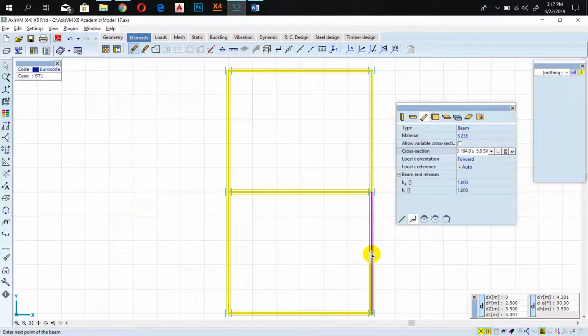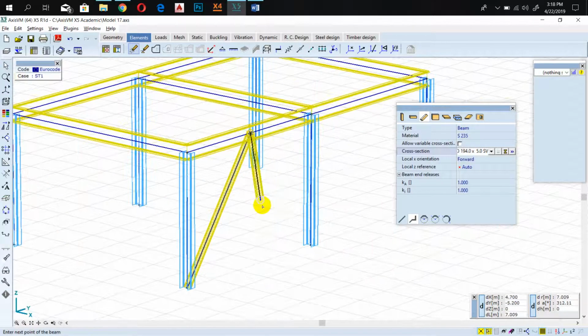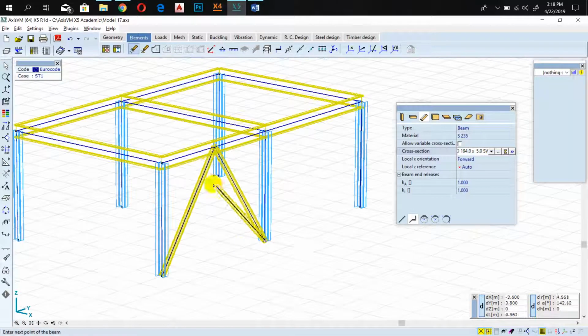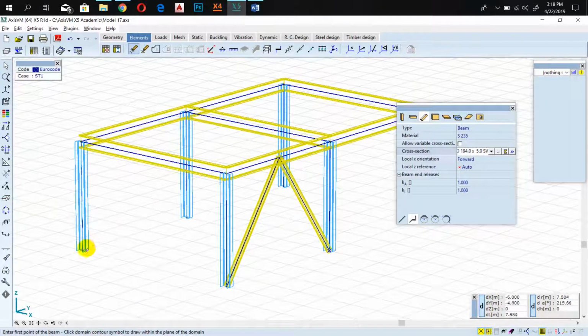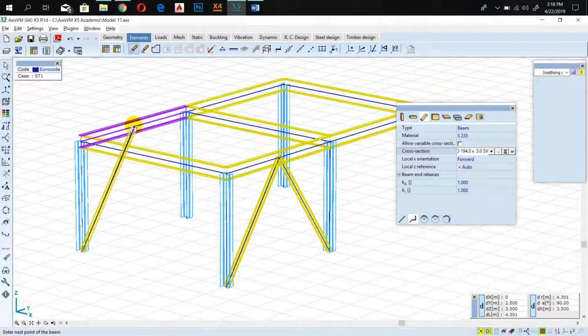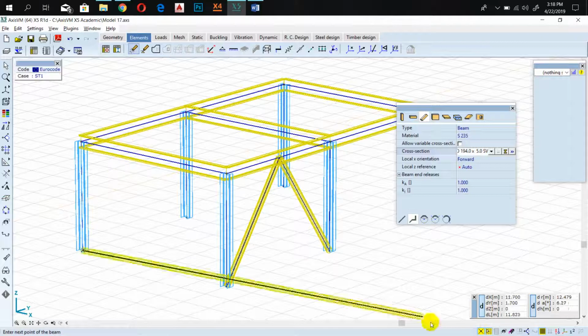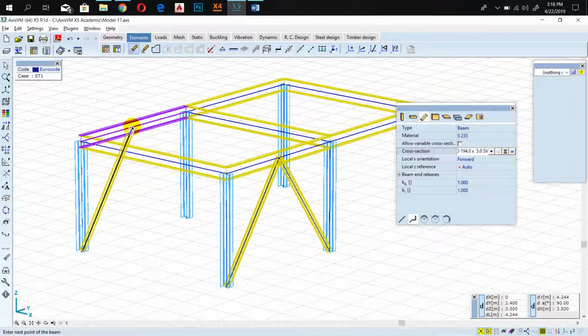So you can go to the top view and you can click in the middle, and then you got the middle point. Okay, and then again you can just change into the horizontal 3D, and you see it is in the middle, or it depends on how you are using. Okay, I just use this to show you how we have to do. And then again click here, and this time I will not use the top view, I will just use this one. I know because when I brought my cursor here, in the corner you can see here the distance. The dy distance should be the 2.5, because I know the actual length. And I will just look at it here without wasting my time, and click here and do here. That's all, and press escape.